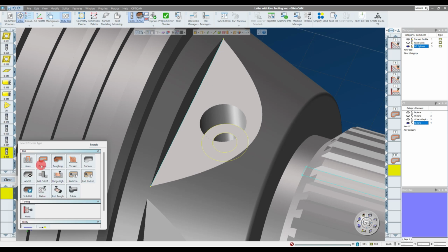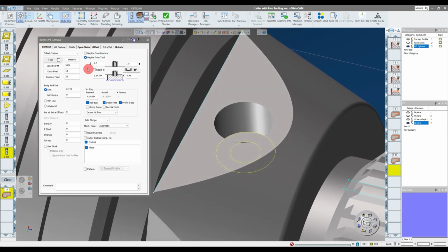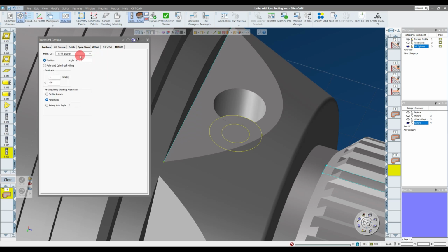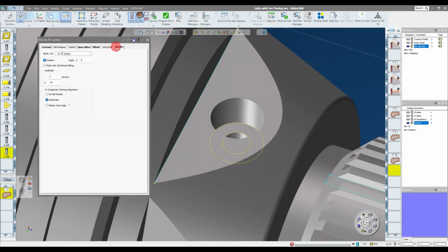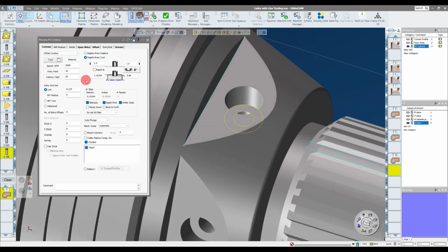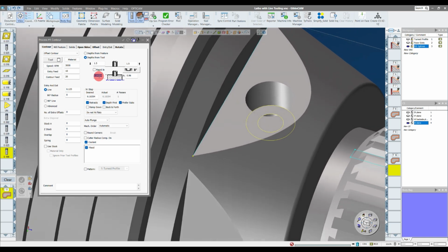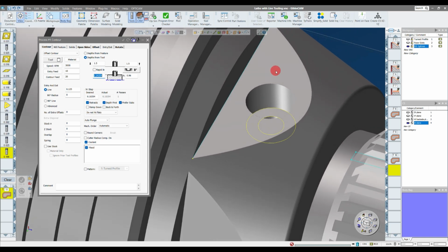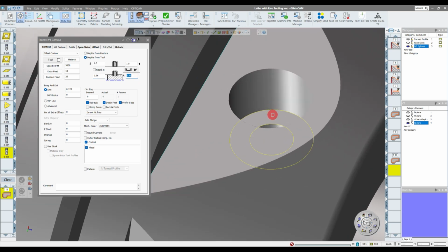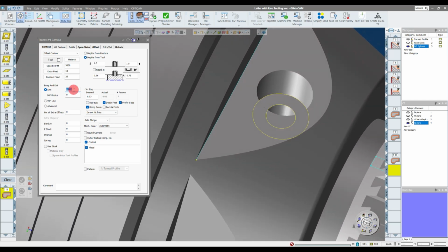So I'm going to bring this tool down, and this is also going to be a contour. So I'm going to make sure I'm in the right coordinate system, which I am. Oops, let me take out my, no, I'll leave the rotations in there. I do need those rotations. So I'm going to find out where is the top of my material that I'm going to be machining, which would be this flat. And then where is the bottom of the counterbore? So I can either interrogate this flat bottom or the vertical wall, because remember, it's going to give me the lowest point. So it's 0.21 deep. And how about a 30 thou depth of cut? I'm going to ramp down, and I'm going to turn off retracts. Now for my lead in and lead out, let's try 10 thou and 10 thou radius.